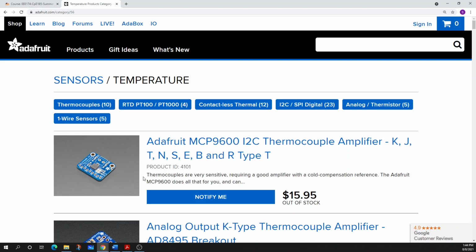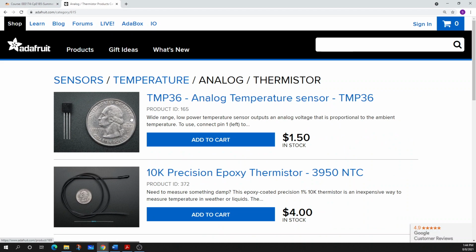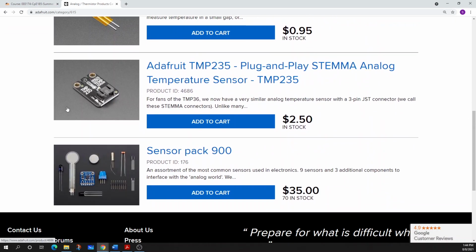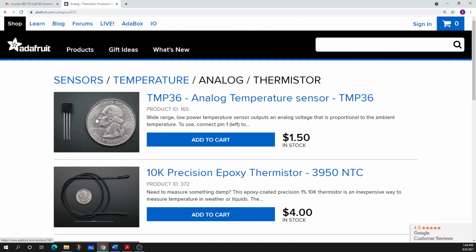The Analog Discovery 2 works great. It has most of the analyzers we need to solve these problems, but unfortunately, we don't always have access to those. So for the purposes of the lab, I want us to focus on analog sensors. There's a multitude of them, and there are some inside your kits. You treat them almost like a potentiometer. The voltage changes based off of the temperature data changing. If it's a different type of analog sensor, the same thing. All we're doing is measuring voltage, which we can use with an ADC. Here I have an example, the TMP36.